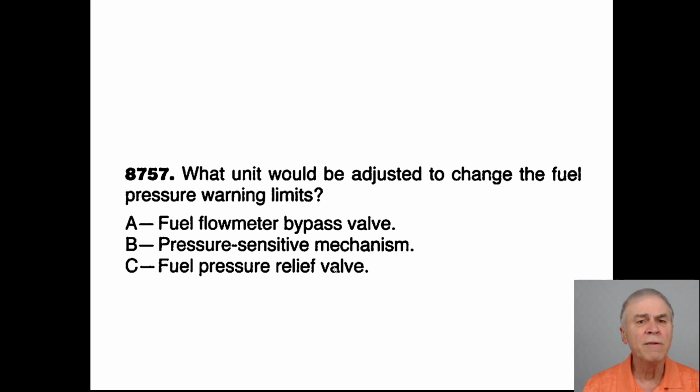The fuel pressure relief valve doesn't really have anything to do with the pressure warning. That's mostly so that if there's excess pressure, it will be relieved from the system. Nothing to do with the warning limits. We're actually warning of low pressure, not high pressure, which is what a pressure relief valve protects against.